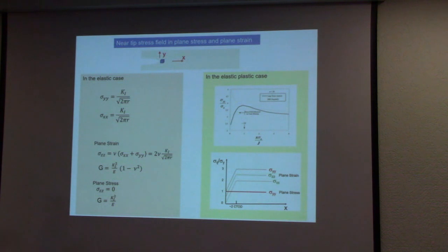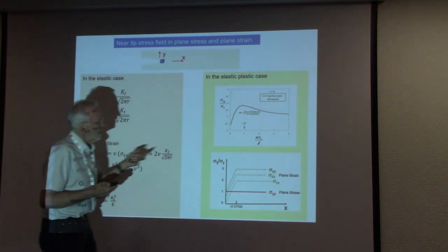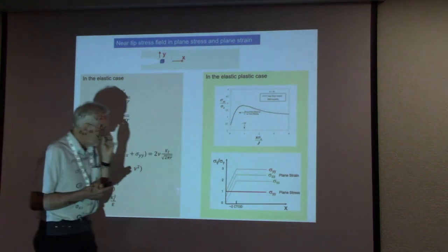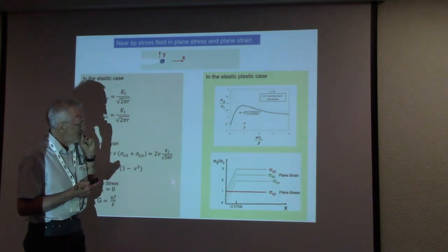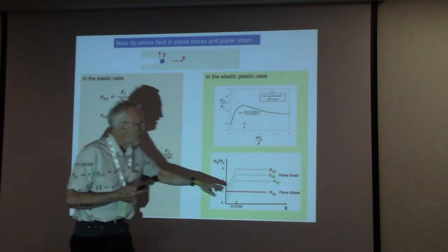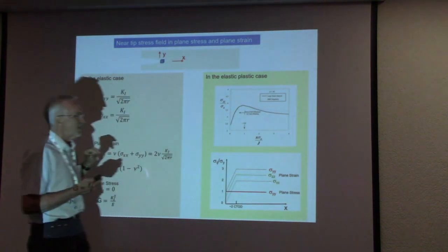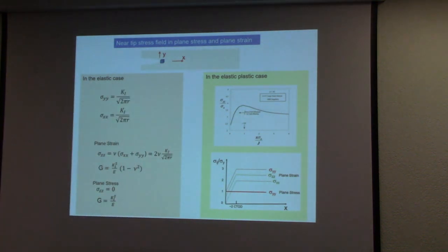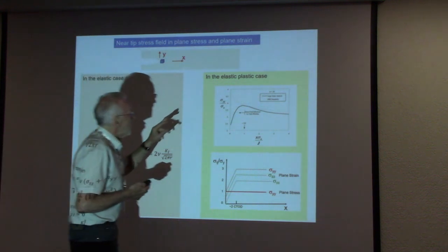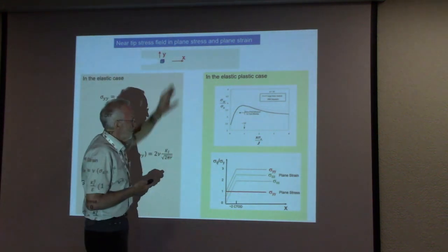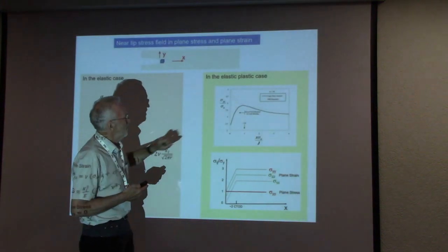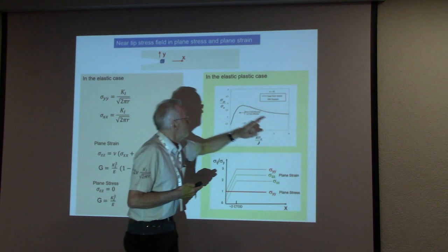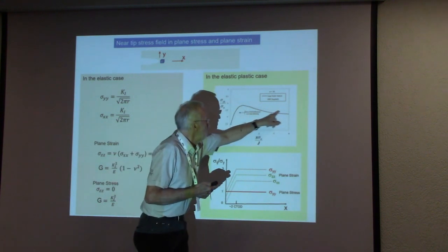But in microsamples and in thin films, you really can also realize a plane stress state relatively near to the crack tip. In the elasto-plastic case, very near the crack tip, this is the HRR solution.